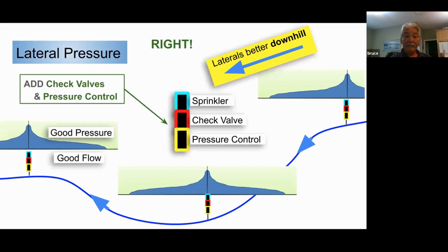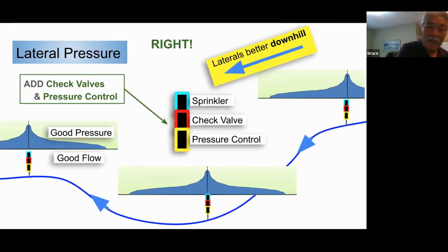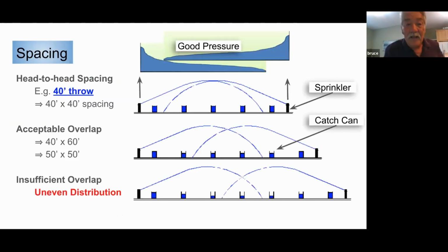Next. So what should you do in some of these circumstances where we have the pressure? We've already addressed that. We can use pressure regulation or flow control regulation underneath each of the sprinkler heads. Relatively inexpensive method of doing it. Also, you can get check valves. The check valve can go underneath the sprinkler head and it's going to affect your low head drainage to a point. I say to a point. For the next slide, please. Okay, I'm bad. It's not the next slide, but we'll get to it.